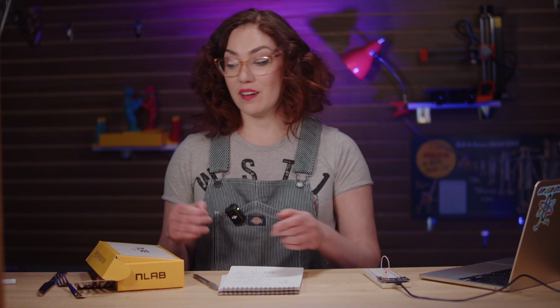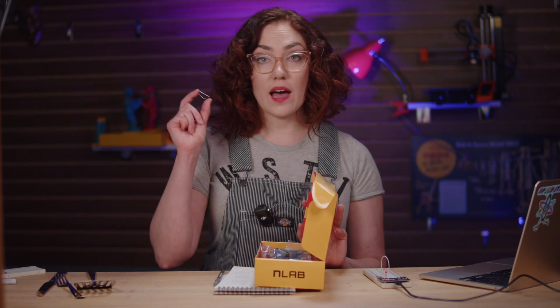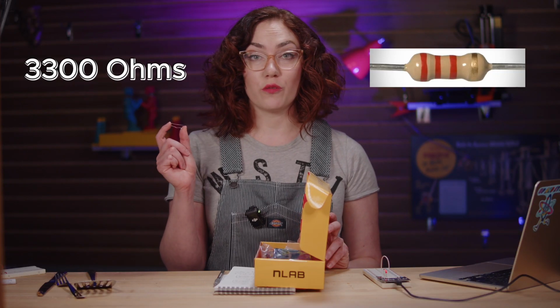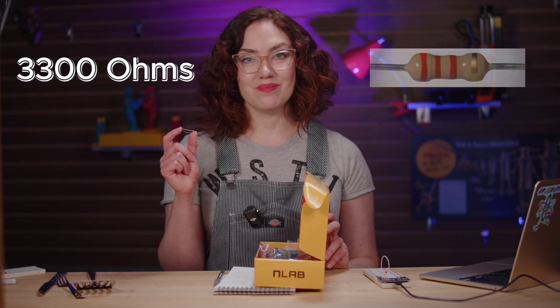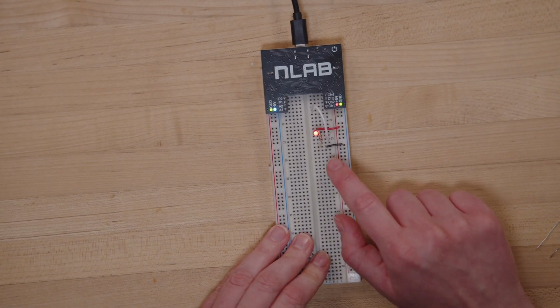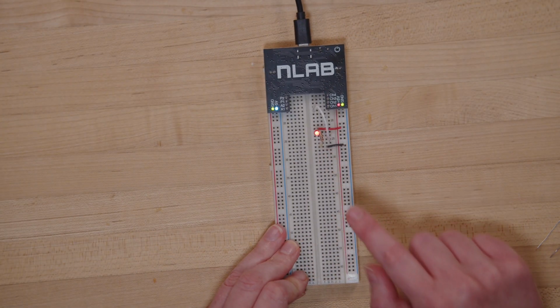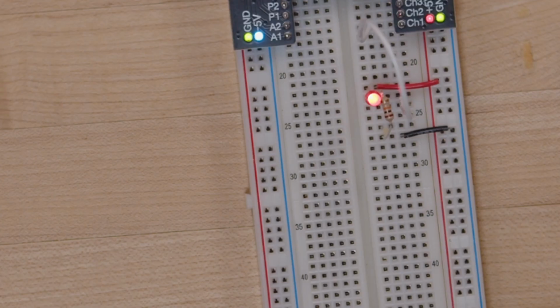That would be a resistor that starts with orange, black, red, but sadly, I don't have that in my kit. I do have orange, orange, red, which is 3,300 ohms. Close enough. I won't tell if you won't tell. Let's build it. I'll keep the circuit that I've already built with the 10K resistor and build a new circuit here that allows me to compare to the new resistor.